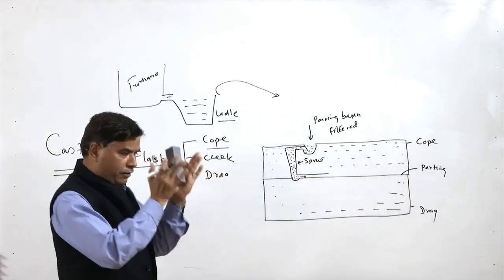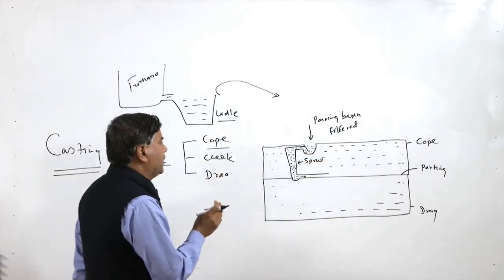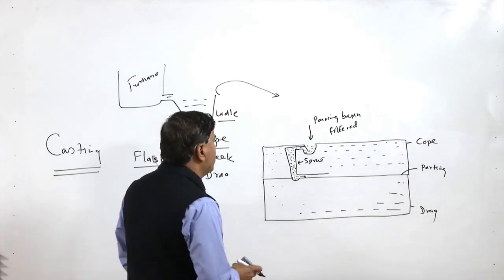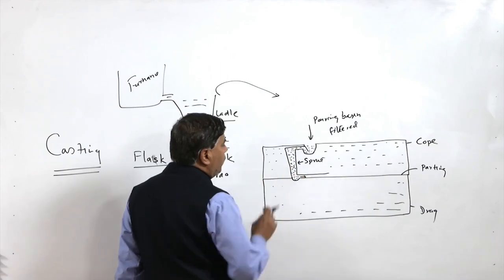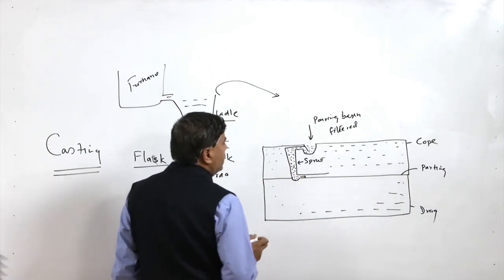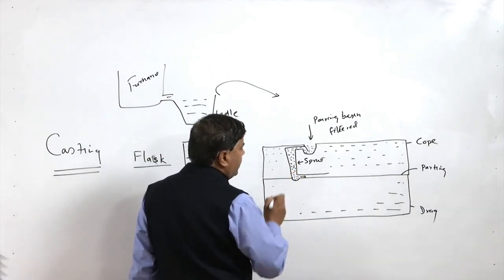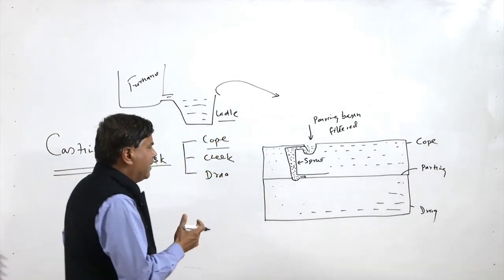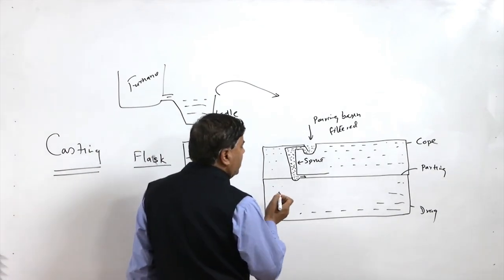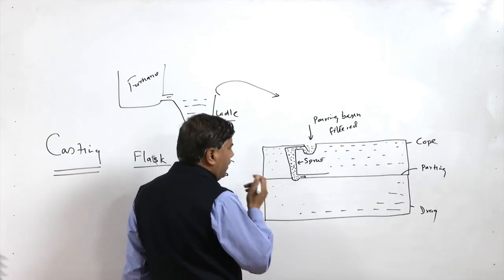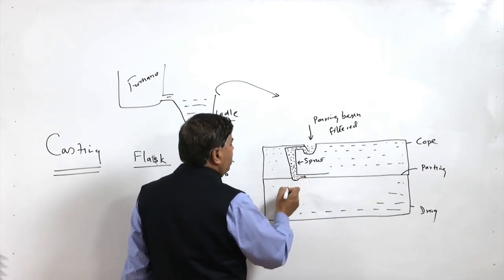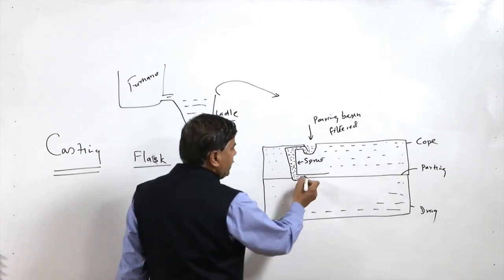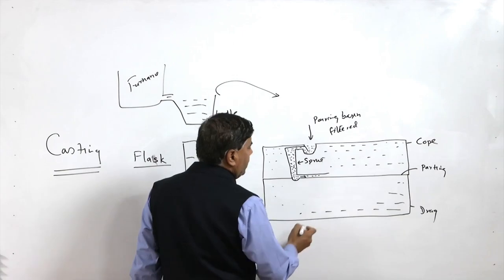This is made with a reducing cross-sectional area so that air aspiration is reduced, and it is always full of the molten metal. So, the air is not sucked into the molten metal and it remains clean, and the gases do not get mixed up with the molten metal. After reaching the sprue base, the molten metal starts flowing into the runner.